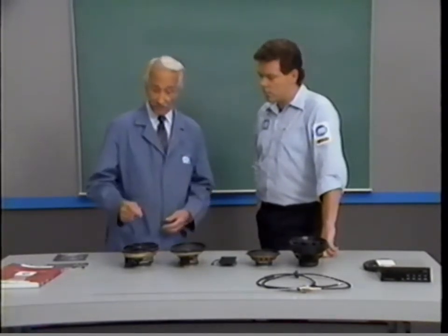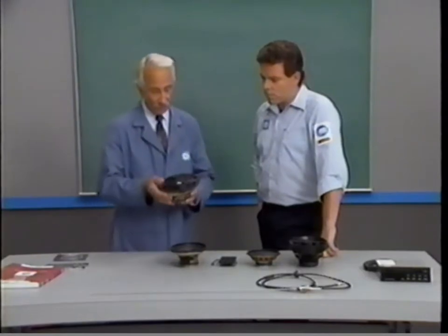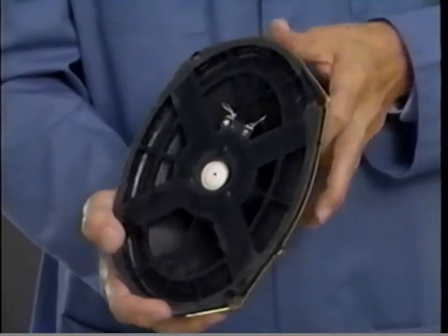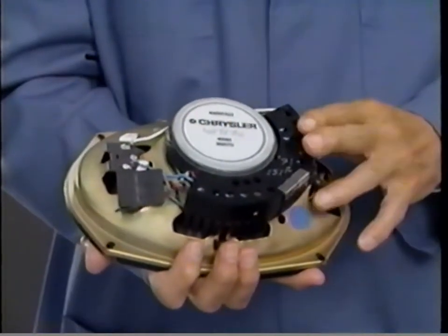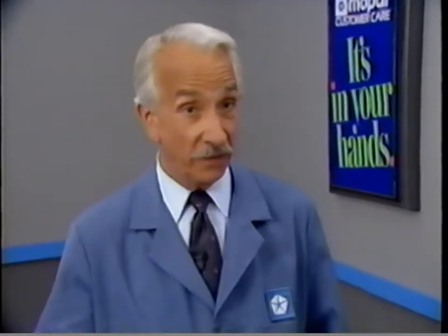Chrysler sound systems use different types of speakers for different applications. On the Chrysler Infinity 1 and 2 systems, you'll find that the Infinity coaxial speakers have separate amplifiers mounted on the rear of the speaker like this. Now, with the amplifier mounted in the rear like that, is it possible to connect these speakers to a non-Infinity radio? Well, yes, you can, but the sound quality will be diminished because each system is custom designed and built for each vehicle. So don't mix systems.